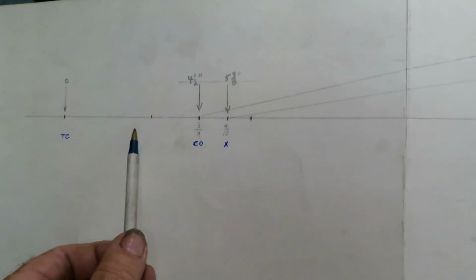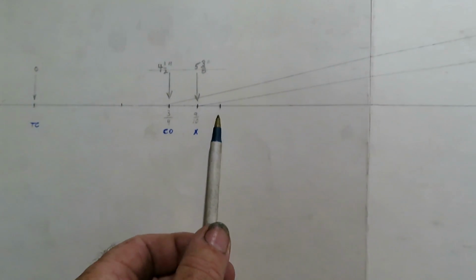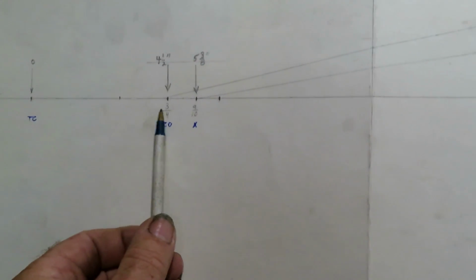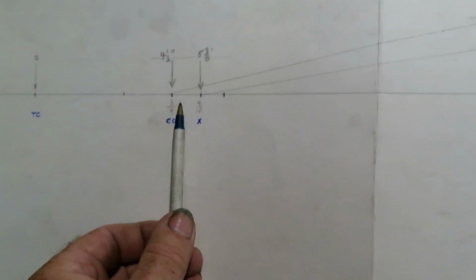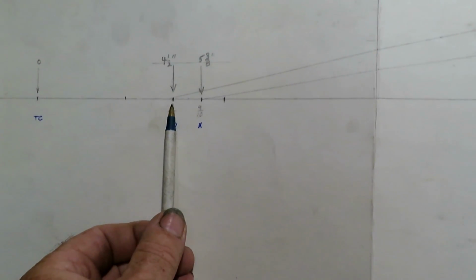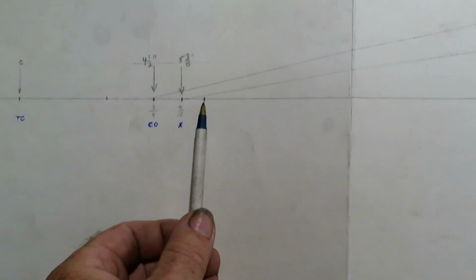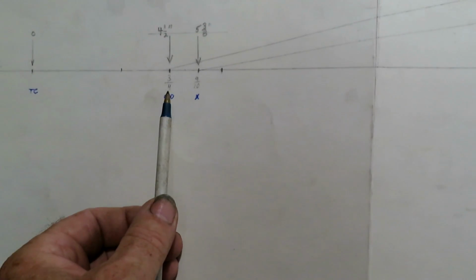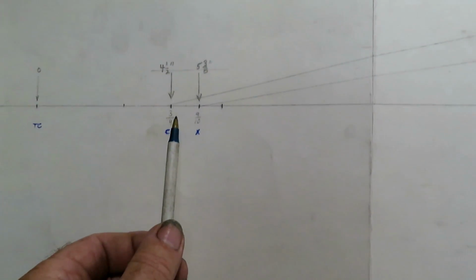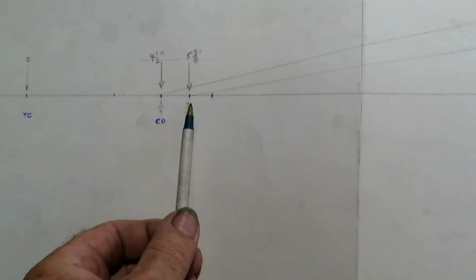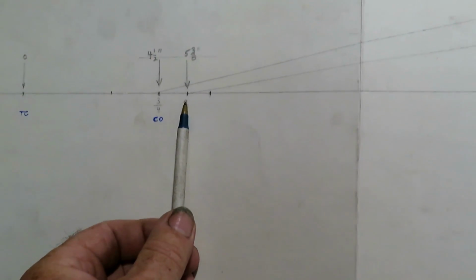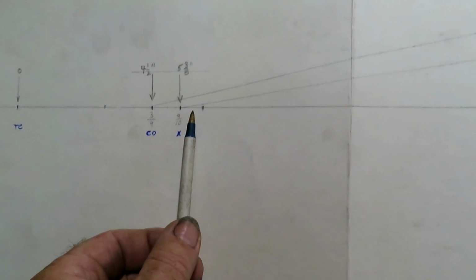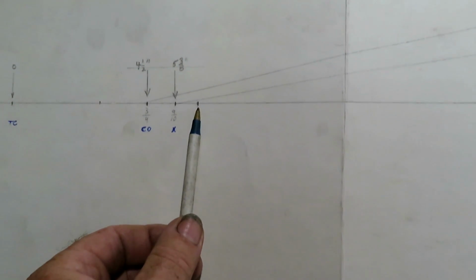You don't let the steam go all the way to the bottom of the cylinder, because it was found to be very inefficient that way. If you cut it off at about 3/4, the steam expands the rest of the way and then is exhausted. So I want the steam to cut off here at 3/4 of the stroke, and then the rule of thumb is to have the exhaust port open at 9/10 of the stroke. So you get the steam started out of the cylinder before it actually gets to the bottom.